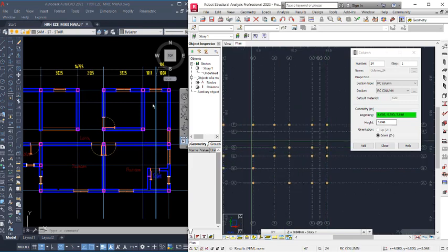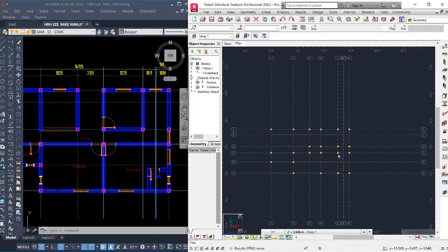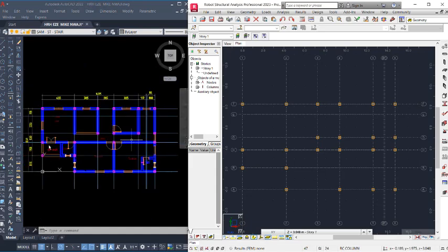This particular provision is for the staircase. Staircase provisions, which is this. So the next thing is the beam members. Let's close it. You have to check closely to make sure that what you're doing is correct. You place the columns according to how it's presented on the plan. So let's still modify this. At this point we wouldn't have any columns right there, green line 3, so we select this and easily delete it. Then we have to place another column right here, at this point.